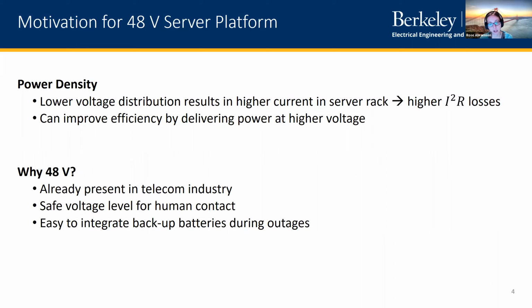And especially as we are shifting towards data centers that consume more and more power at the server point of load, this is becoming a much more efficient way of delivering power by using this 48-volt bus. And the reason why they're choosing 48 versus maybe 70 or 100 volts is that there's a lot of legacy in the data center infrastructure that makes it easy to kind of switch to 48.